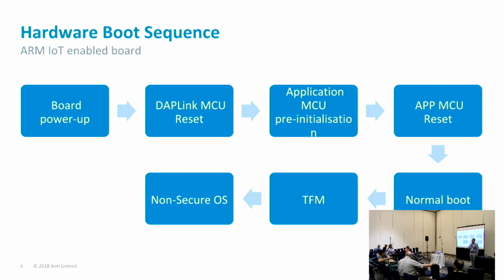Okay, but if you do that, we also have NV counters that prevent rollback of software. So once you've built this testing thing, you can't go back to the production one. You have to go forward. You know what I mean? And again, like I said, you can't turn off the secure boot, can't undo it. Once you set it, it's permanent.